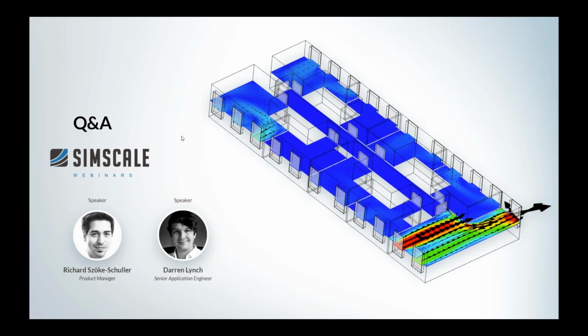Really, to mitigating counter stack effects in tall buildings, what we would really identify this as helping to do would be to better visualize the flows, identifying the flow paths within the building. And this is really going to help us understand what about the building's construction is allowing this draft to go through, countering the stack effect. So we're really going to be identifying high pressures. We could identify high pressure facades on the outside. That would be, of course, an easy inlet for the flow, and low pressures as the outlets.